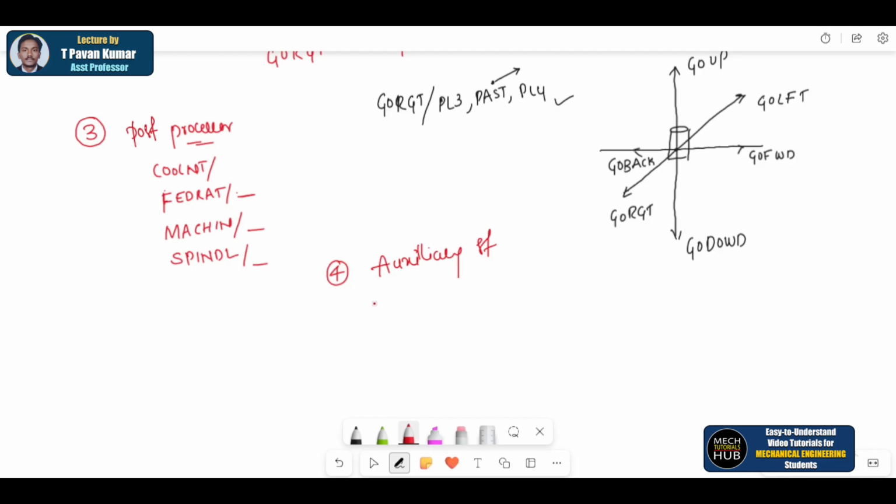If you want, you can give it, like if you have any internal tolerances or cutter radiuses. If you give them, then it is fine. If not, it goes with the default outer tolerances. Then slash, finish the program, FINI to finish.